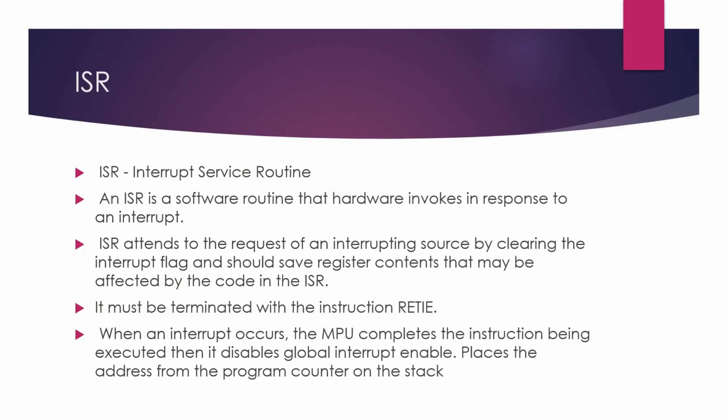Then ISR. ISR is nothing but an interrupt service routine. An ISR is a software routine that hardware invokes in response to an interrupt. It must be terminated with the instruction RETIE. ISR attends to the request of the interrupting source by clearing the interrupt flag and should save register contents that may be affected by the code in the ISR.